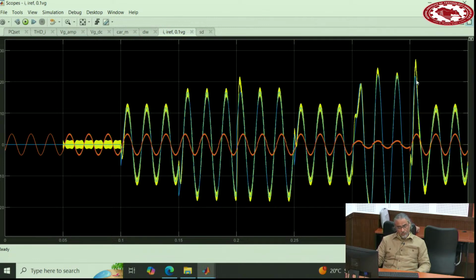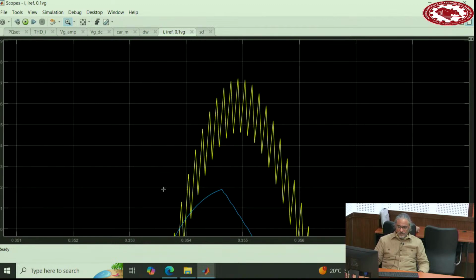So the current limiting, as I explained to you, is a challenge. Especially in AC, we hardly manage to completely limit the current. So sometimes, for a very short amount of time, the current goes above what you really designed. First of all, because the time is very small, switches should be able to tolerate it. Secondly, if your switches cannot tolerate it, you need to make sure that when you purchase them, you purchase properly so they can tolerate that level. But I believe this amount of time should be fine for all the switches that we have.